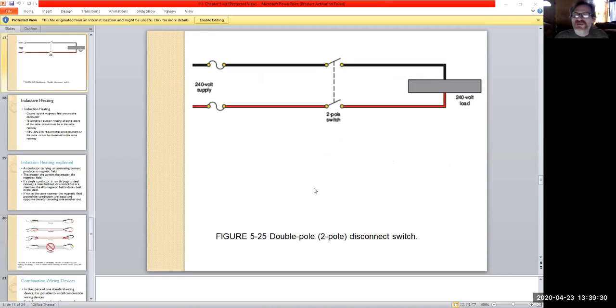Anyway, so then we get into one, and we talk about poles, okay? In this case, we talk about a double pole. What that means is you would have two switches, and for whatever reason, they have some kind of mechanical bond across them. Some breakers are wired up that way where you'll see a metal tab going across both switches where they can't be operated independently.